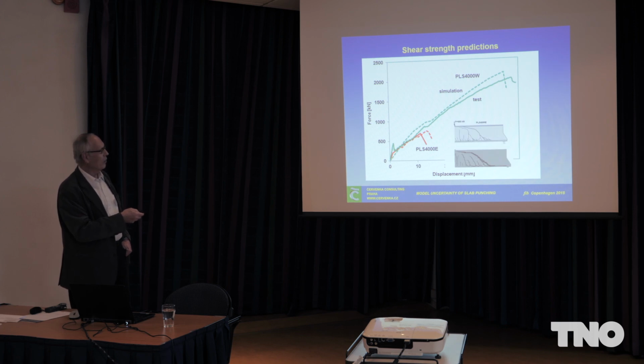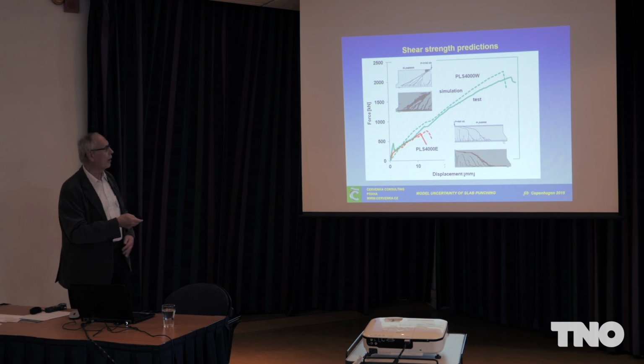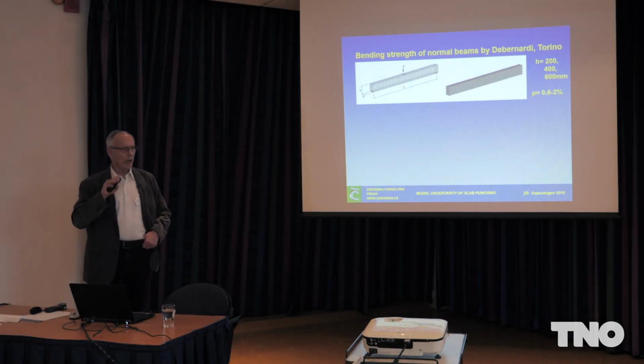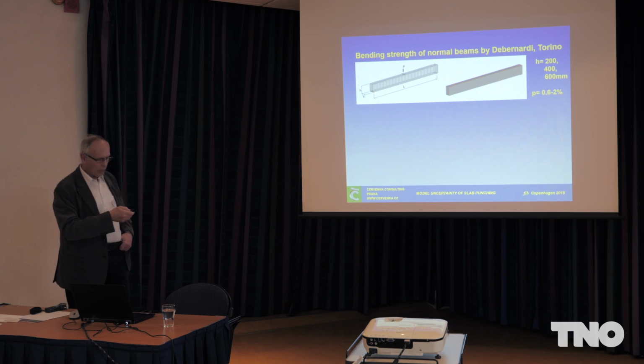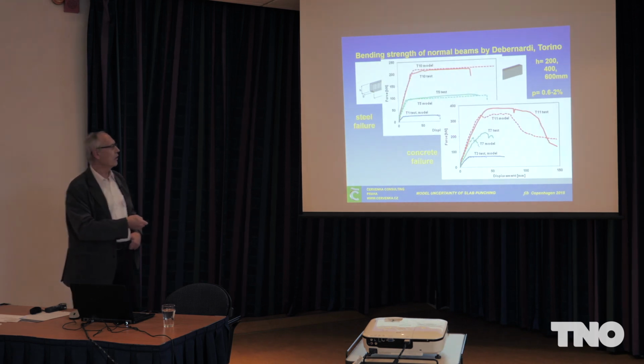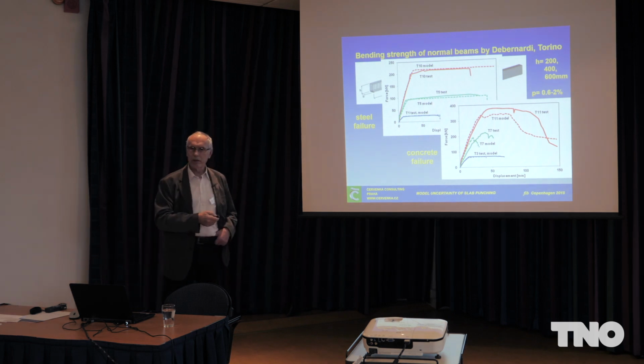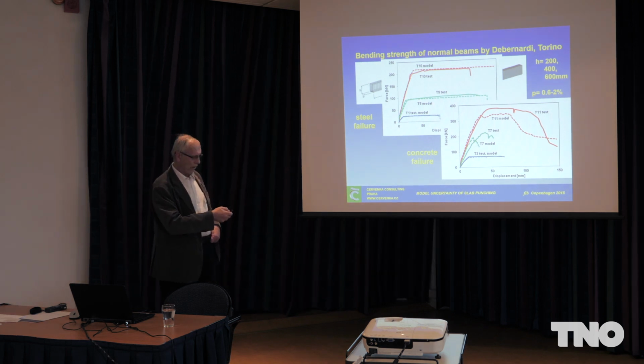Okay, so you see this is crack pattern, experimental, simulated, and the other one is tensile failure, more or less, and the other one is tension compression failure. And now I come to the third class of problems, which are beams tested in Torino, different sizes again, different reinforcing ratios, simulations of ductile behavior, simulation of brittle failure, and in this case the brittle failure is compressive failure of concrete. I always have difficulties to push the run button.